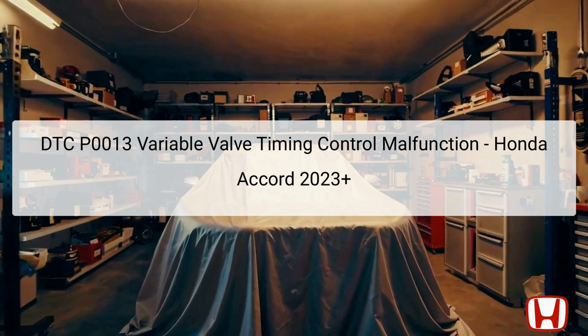The DTC P0013 indicates an issue with the variable valve timing control, or VTC, specifically related to the oil control solenoid valve B in the Honda Accord 2023 and newer models. The VTC system is crucial for optimizing the engine's performance and efficiency by controlling the timing of the intake valves. If the oil control solenoid valve B returns an abnormal signal, the powertrain control module, known as PCM, will flag this issue and store the DTC for reference.